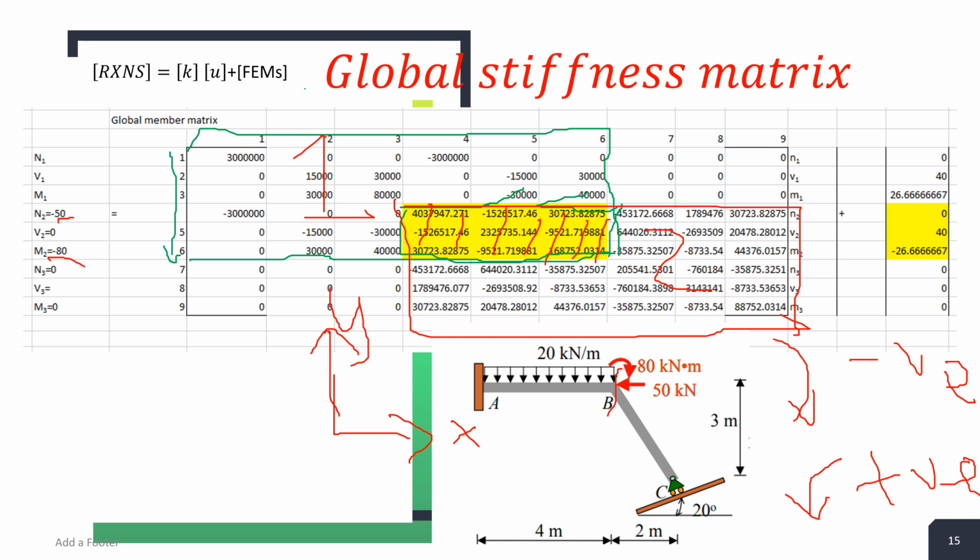So that's one thing. Also, this is a hinge. We need to know that at a hinge, the summation of moments is 0. So we know this, which is why I state that you need basic understanding of mechanics of structures. So we know that when there's a hinge, the summation of moment is 0.